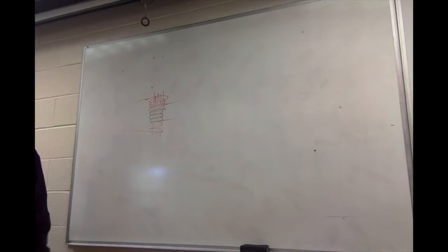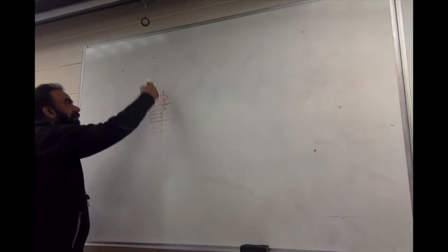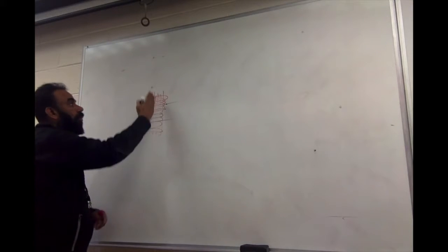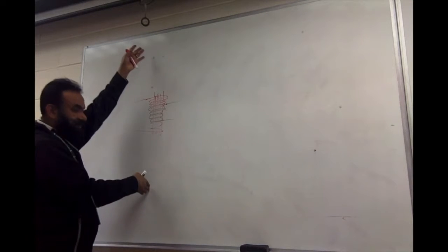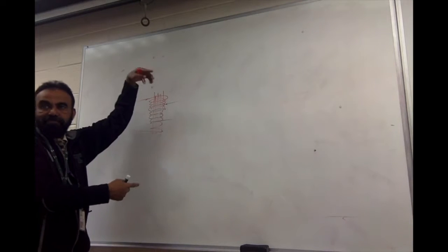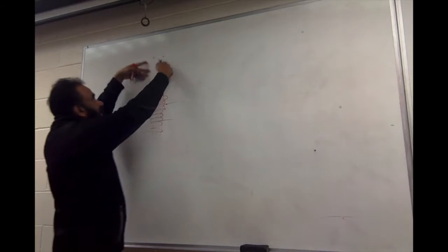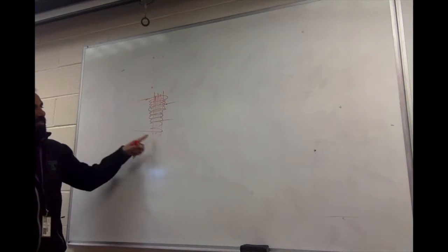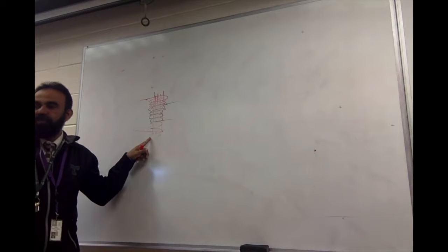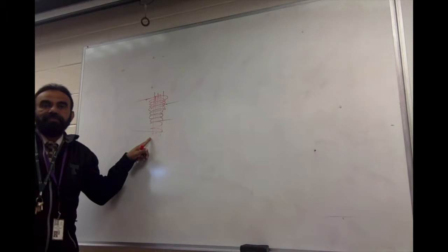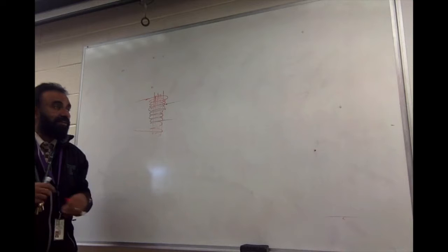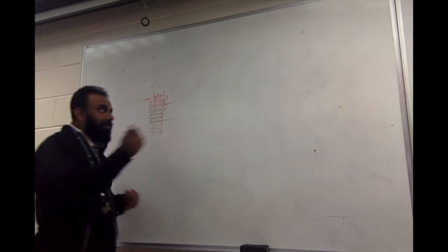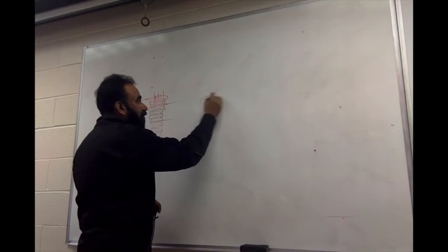But the problem with this transformer is the magnetic flux which is produced in the core is lost. It's kind of lost like that, and this side is also open. So this won't be a very efficient transformer because we are having magnetic losses. Now, if you don't want the magnetic loss, and we want to trap everything inside, then this is one thing you can do.